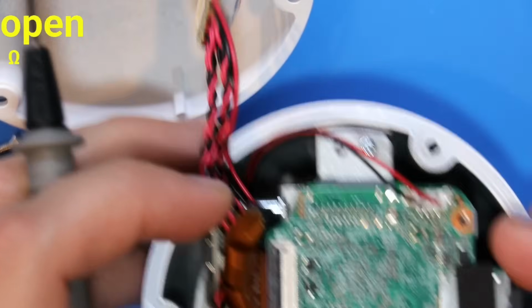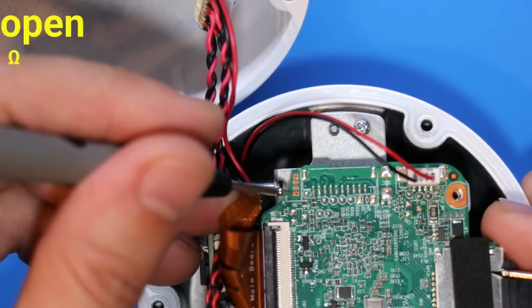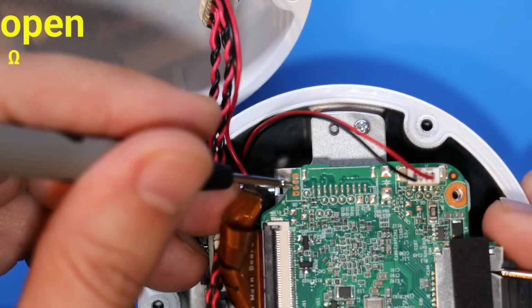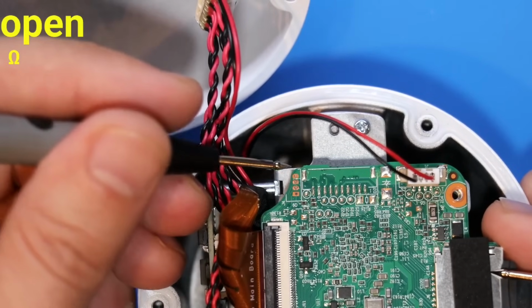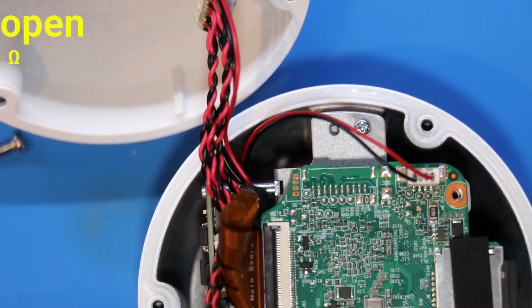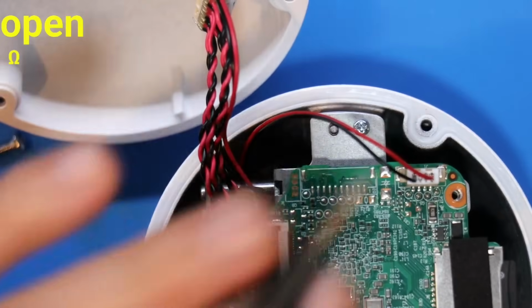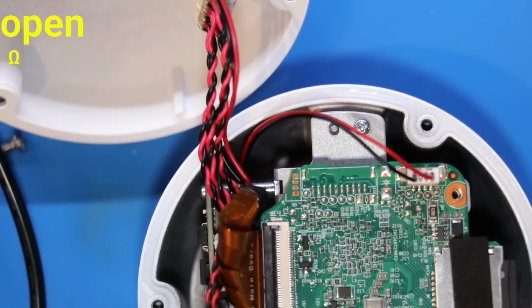So now I can hold on the SD card slot and probe here. Nope. All right, so that top pin is ground. That means I don't have to worry about that one, so I've already eliminated one out of four. What we're trying to hunt for at first is the device's transmit pin, because what we're going to look for is a fluctuation in voltage, especially when we boot up the device.